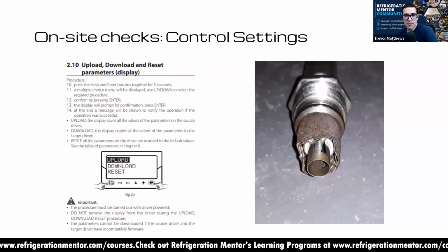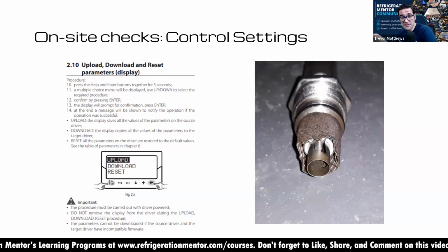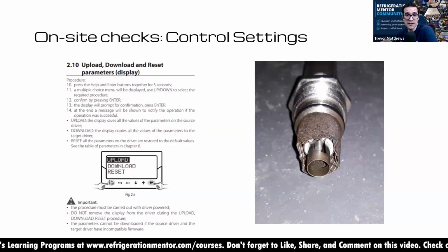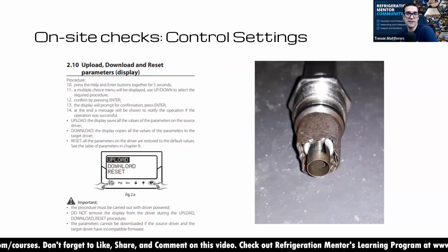Now, your high pressure valve is really the control of your system. It's controlling your gas cooler condenser. It's controlling your receiver. And then you start plugging that up, it could cause issues in a lot of different places. You could be out at a case, and that last case is not feeding. You could be looking at the flash tank, the high pressure valve goes into the flash tank receiver, but it could cause some issues in other places in the system, but it comes back to the flash gas.